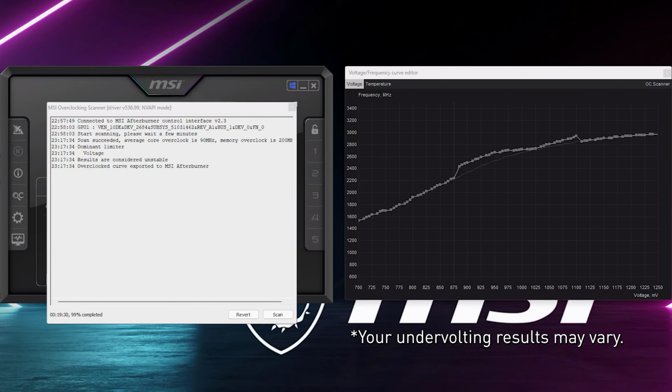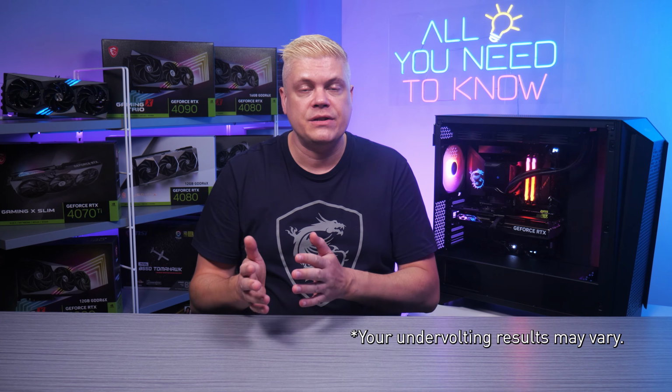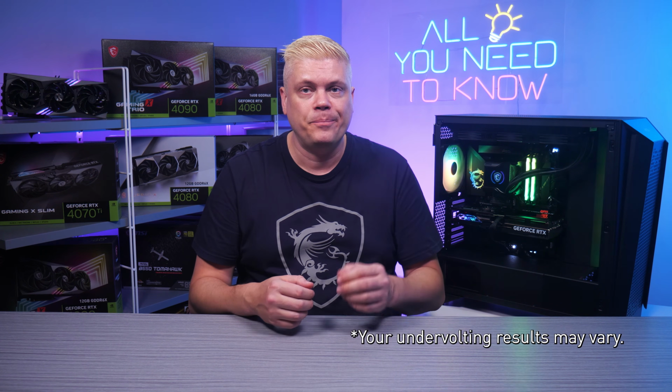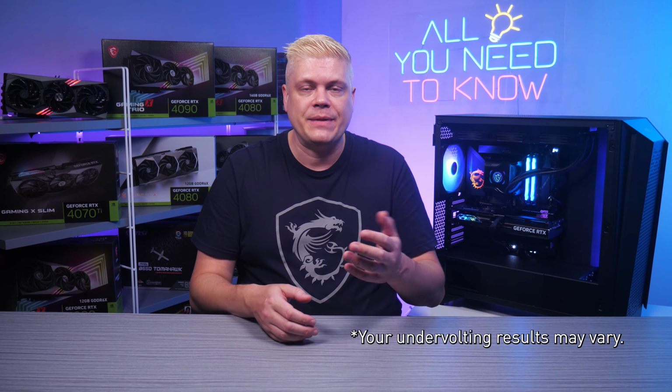You can use undervolting in combination with OC Scanner too, so run OC Scanner first and save it to a few profiles before you start. And you'll generally see actual results with mid to high-end GPUs, though monitoring and tweaking an aggressive undervolt could be tedious in the long run. And thanks to Tech Illiterate and Techia City, whose undervolting videos really shaped this section.